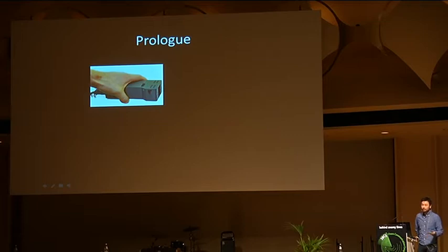They relied on Vicon trackers and also required the user to specify the room geometry to truly interact with the surfaces. So we looked into tracking solutions in robotics, which didn't rely on infrastructure and which could simultaneously locate and map the environment just by using a laser range scanner and a video camera.